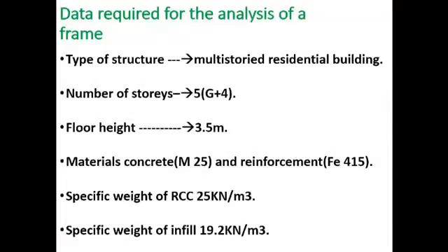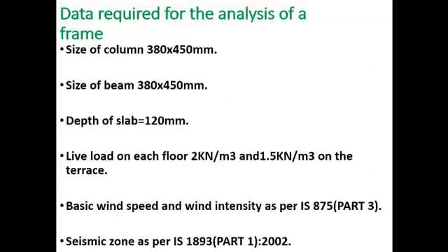Data required for the analysis of frame. My project's type of structure is multi-story residential building. Number of stories 5, floor height 3.5 meters, M25 concrete and Fe415 steel. Specific weight of RCC is 25 kN per meter cube. Specific weight of infill is 19.2 kN per meter cube. Size of beam and columns are 380 by 450 mm. Depth of slab is 120 mm.